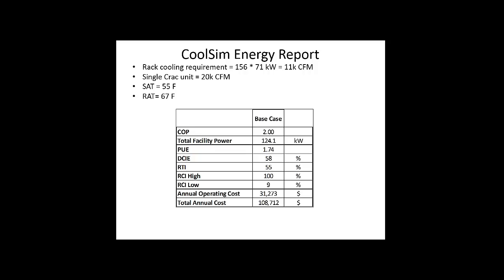And the consequence of that is that the RCI low will be very low because we're overcooling. So we have too many temperatures too far down, whereas the RCI high is fine because naturally we have cooled down this whole data center, so there are no hot spots left.